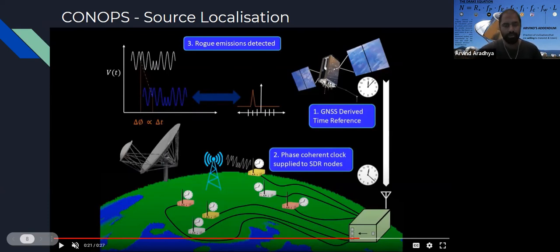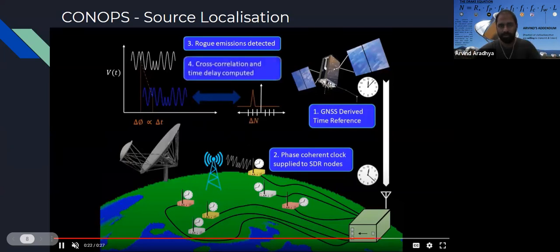And then what you do is something called cross correlation, where you basically slide those two waveforms against each other, and then you integrate, and you get a peak whenever the waveforms overlap with each other exactly. And then you know how much you've slid it by, so that tells you the time delay that actually exists between the transmitter and the receiver. And you do that for all of these different radios. Between any two pairs of radios, which are color coded in the same color here, you have a constant difference in arrival times. And if you solve the math for that, you get a hyperboloid, which will construct a hyperboloid on the surface.